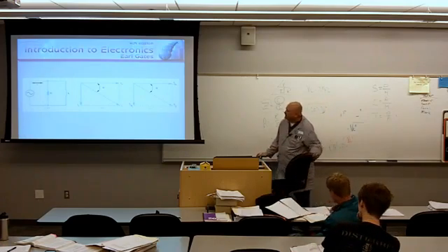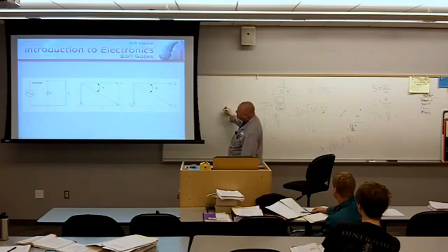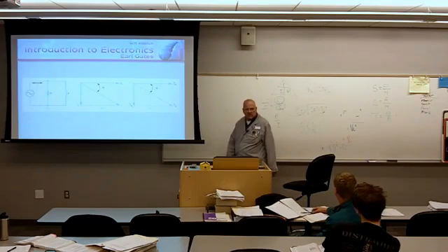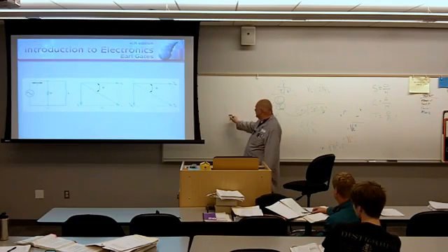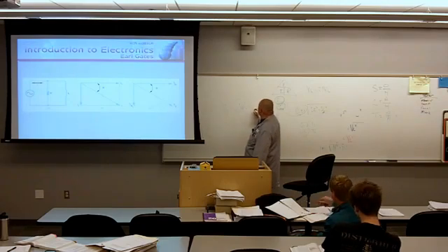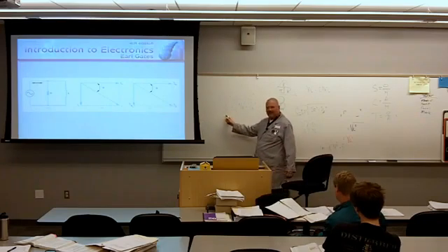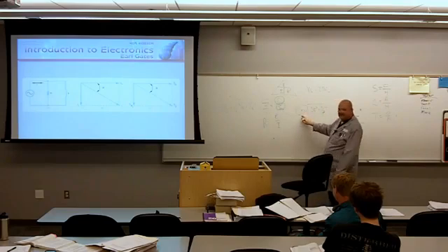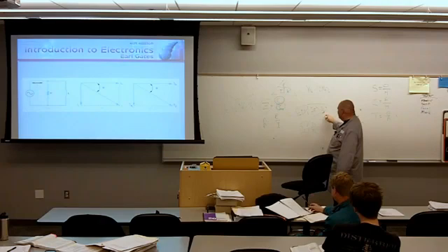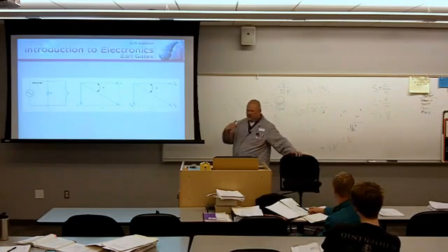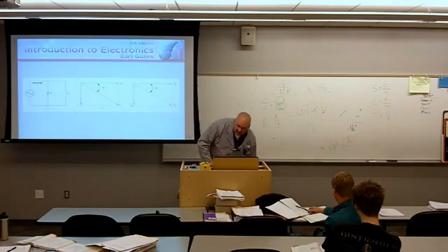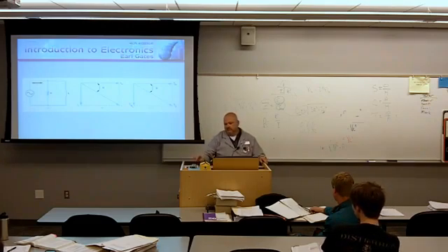So IT is the vectorial sum, absolutely, has to be for this kind of circuit. So this would be like IZ is equal to the square root of 1 over R squared plus 1 over X sub L squared. Don't. It's a lot of keys you have to hit for a simple question. You want to calculate your total impedance: Z is equal to E over I. I you get from IT, the vectorial sum of current through the resistor and current through the inductor. You calculate current through the inductor by calculating voltage of the inductor over inductive reactance. A lot easier. So don't do what the book tells you to do. If you want to play with this and just see if you can do it, and hey, look Mom, no hands, cool, do it. But beyond that, I'd stay clear of that formula.